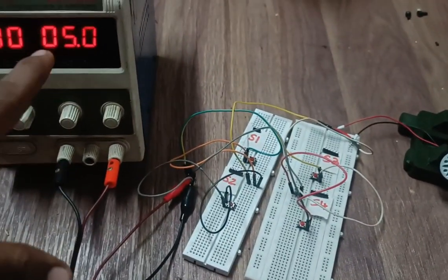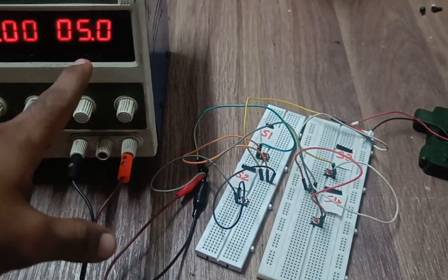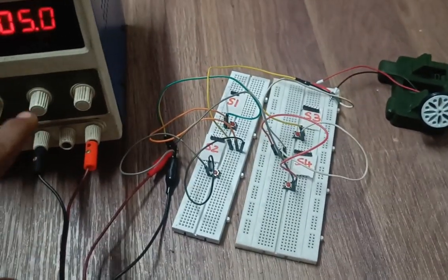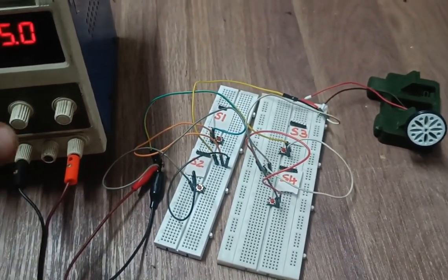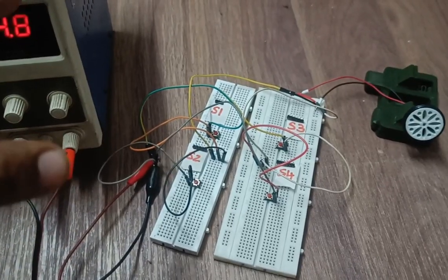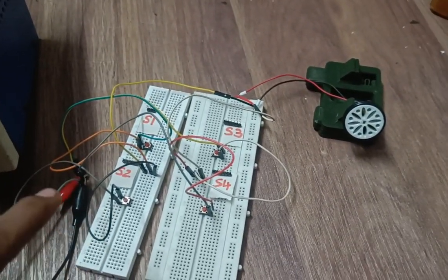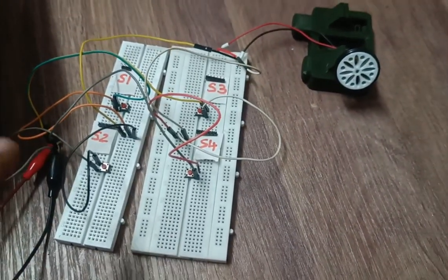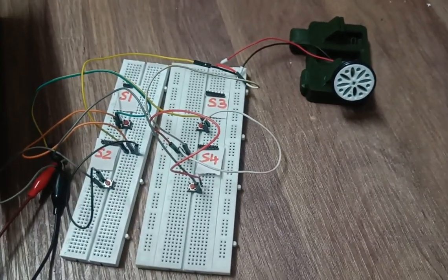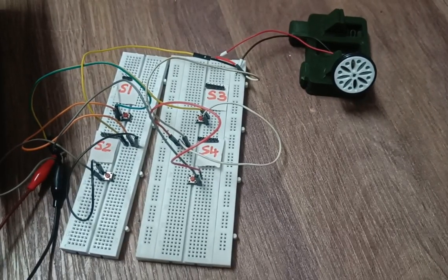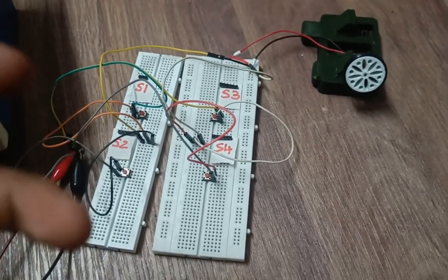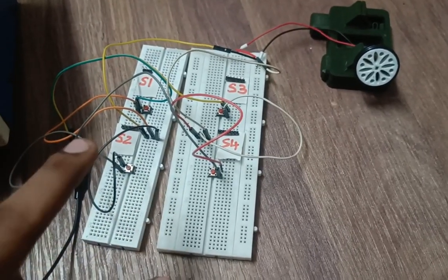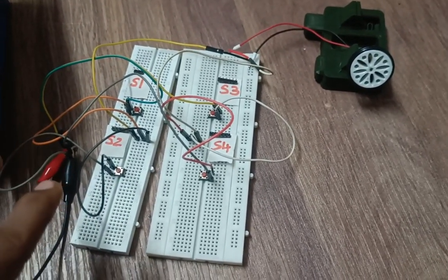Okay, it would be directly controlled by the voltage supplied by us, but we have a method called PWM, pulse width modulation. In that method, we can also control the direction. We can also control the speed of the motor. So together we will have a motor driver. Okay, it's called a motor driver, which can control the direction as well as the speed of the motors. Okay, these are the advantages.